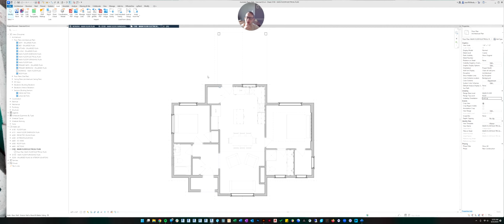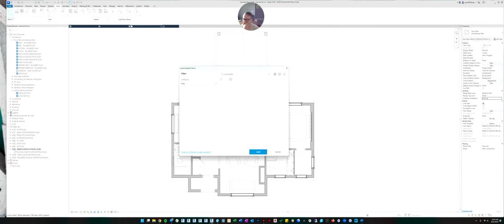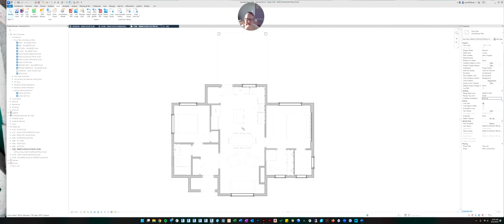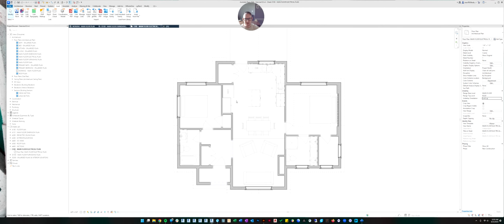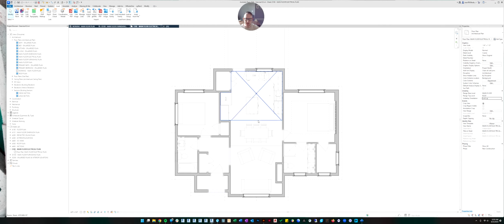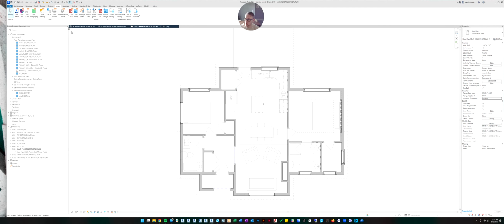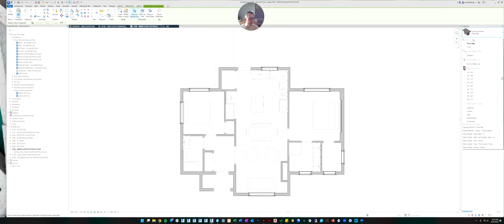Okay, so we got our outlets, our lights. Now we need, what else? Switches. So let's put in light switch. Hit enter. Lighting switches. Let's try that. And load that in. Okay, so now I think we have all the families we need. Let's start placing them. I think we'll start with the outlets. So go up to architecture, you'll hit component, and then let's just type in outlet to find the outlets that we loaded.